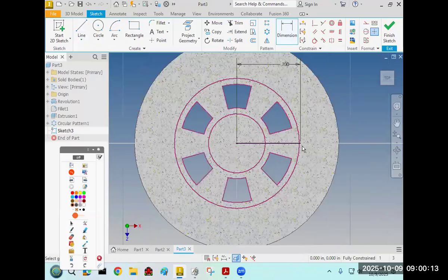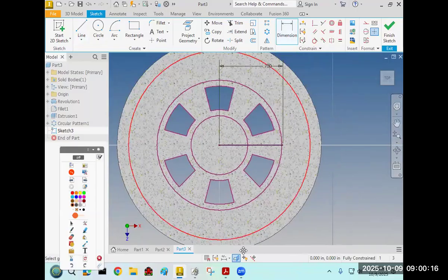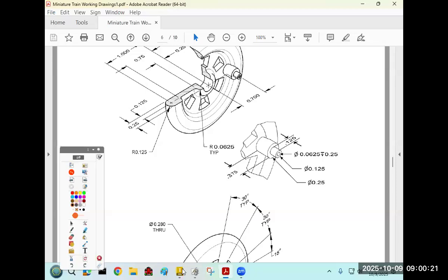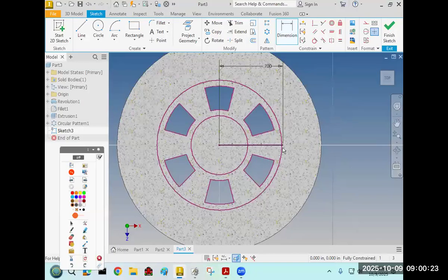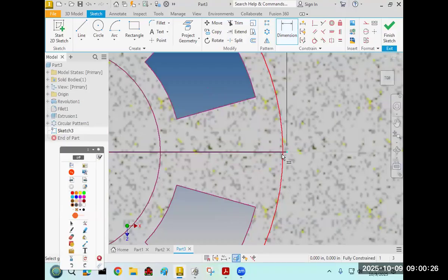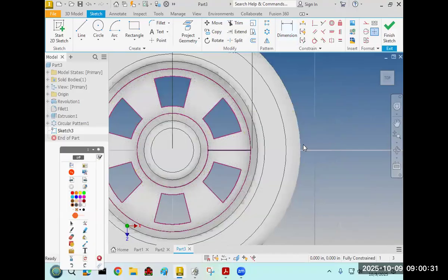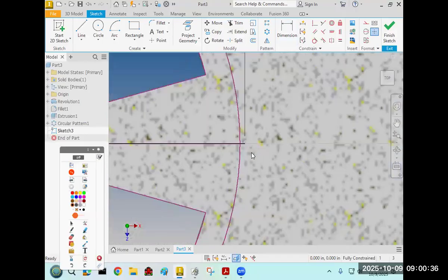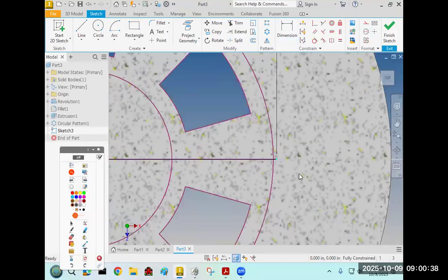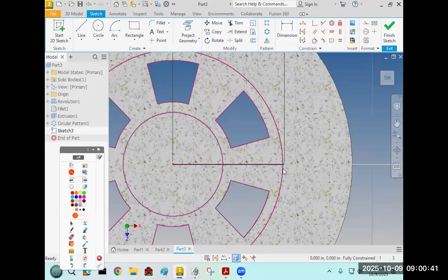What that means is the endpoint of this line is going to be our starting point for our first extrusions. But like I said before, look at how this endpoint is very close to the line that is sort of the edge of our fillet. So when we do our circle, you've got to make sure that you're using this endpoint here rather than something else. Otherwise you're going to have to come back and fix it later. Okay, this isn't an aesthetic thing. This is where things are going to connect.